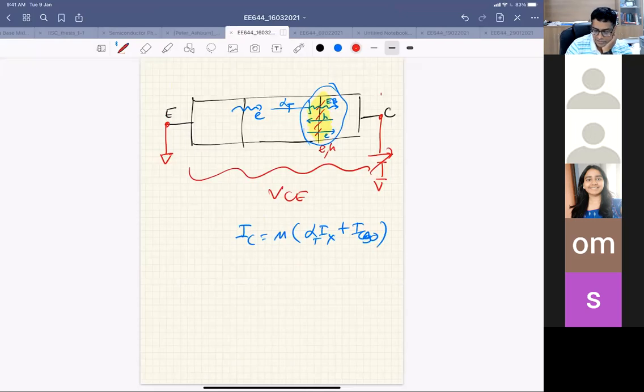These electrons will go to the collector because there is a field from collector to emitter-base, so electrons go in the opposite direction of the field. The holes come to the base, but the moment they arrive, they have nowhere to go because the base is open, so they are collected. Impact ionization is happening, electron-hole pairs are generated, and holes are being collected.